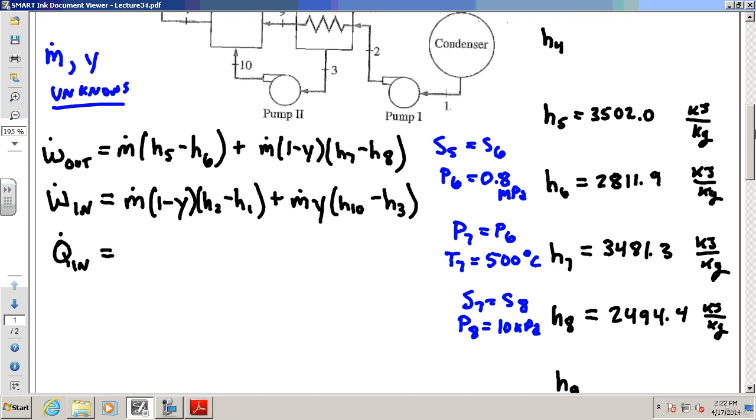I think we can at least do the M dot with no Y's next to it. Good. Times the difference between H4 and H5. Yeah, which would be H5 minus H4, right? Yeah, that's good. That's the main part of the boiler right there. M dot times (H5 minus H4), and yes, all of the mass flow goes through the boiler. But then what about 6 and 7? We've got to add those too. It goes in there too, so plus.